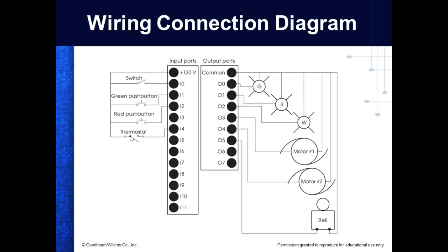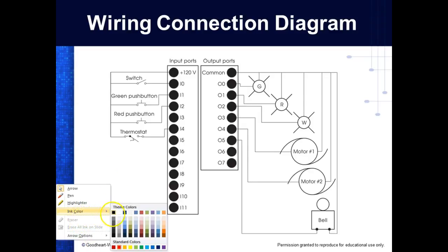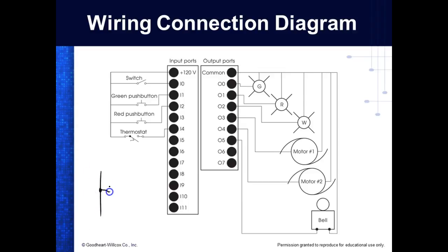So what you do in your ladder diagram is you say, I'm going to use this input to control this device. I could do more than one input. I'm not going to do all the addresses. I'm going to say input 0, and then input 1. You can do that, no problem at all. And then eventually we're going to assign it to an output port.